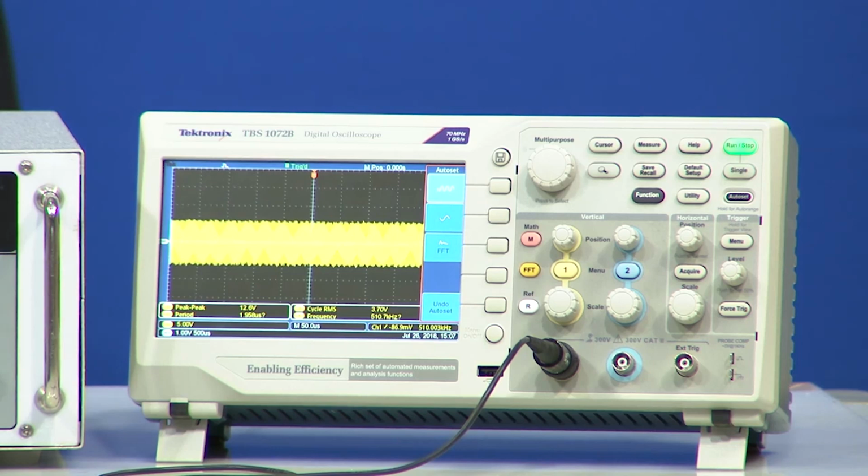For that gain we are getting faithful output only till around 300 to 400 kilohertz, depending on the threshold or constraint that you keep. After that it is coming down, correct, with our gain of 2.2. Now let us see the other circuit.